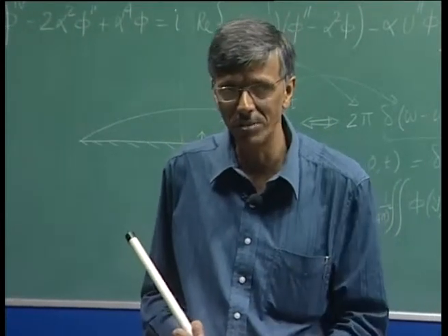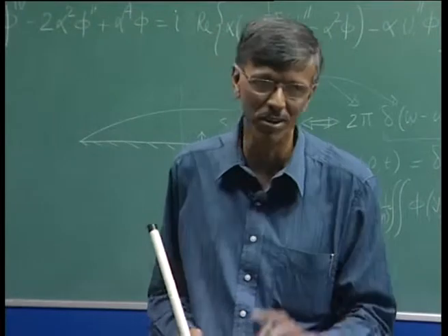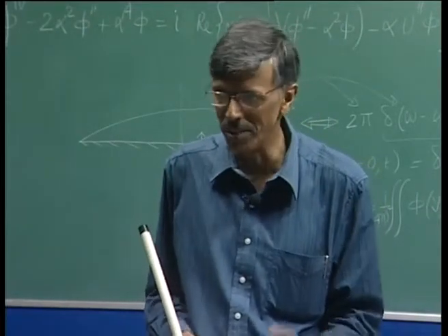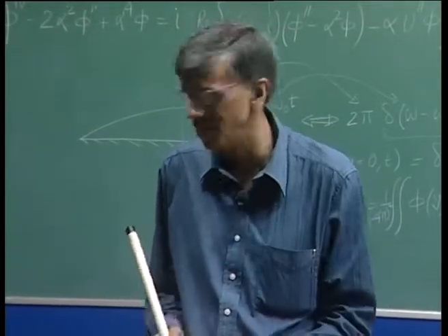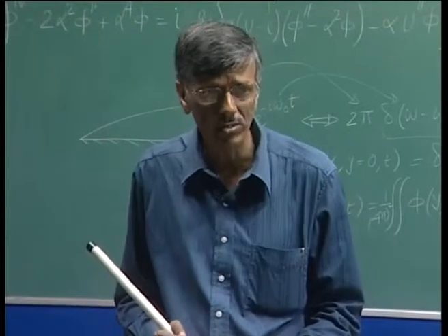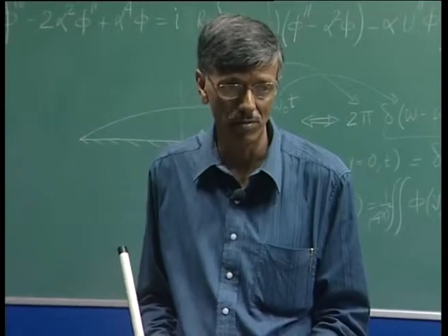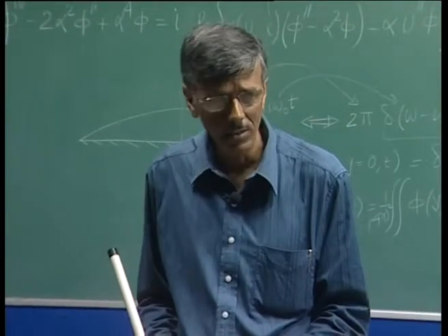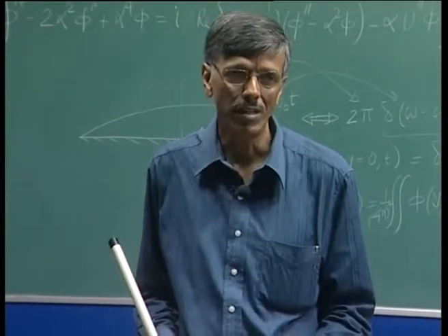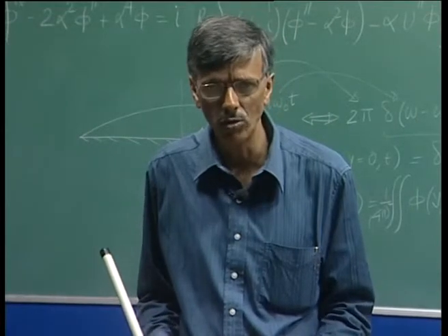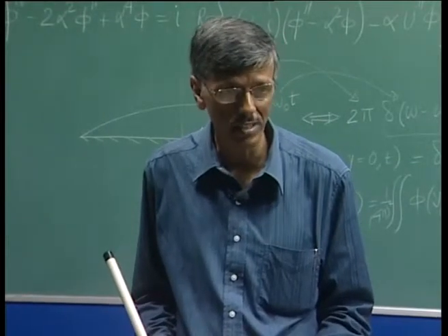And that was your question in the mid-sem. Reynolds experiment relates to, is it a question of nonlinearity or is it a question of receptivity? To me, it appears it's a question of receptivity. If I can stop the background of that particular class of disturbance where the dispersion relation resides, I won't have that response. And that's why people have gone ahead and obtained Re critical for flow past a cylinder to a very, very large value. That has gone as close to as 100,000, while Reynolds obtained it around 12,830.